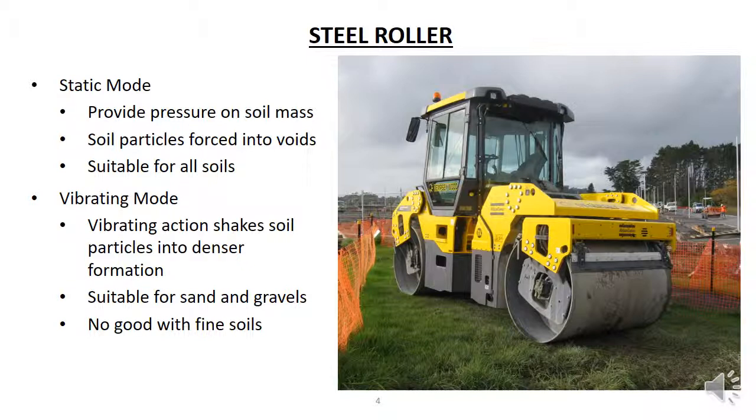However, the vibration mode is not suitable for some fine soils as it can create liquefaction. Care also needs to be taken to avoid overcompacting the soil, especially in vibrating mode, as overcompaction can break the soil particles, or it can vibrate the surface particles out of the soil mass and actually loosen up the surface. Therefore, the last few passes of a roller are in static mode to tighten up the surface.